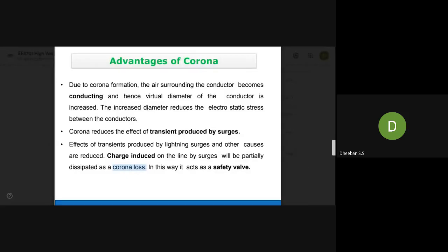So in this, what they are saying is, if there is any kind of maintenance over the transmission line, then before doing any maintenance or repair work, the linemen have to check whether there are any static charges over the transmission line. If there is any kind of static charge, it will be a life-threatening phenomenon. The static charge can cause heavy damage to the body.